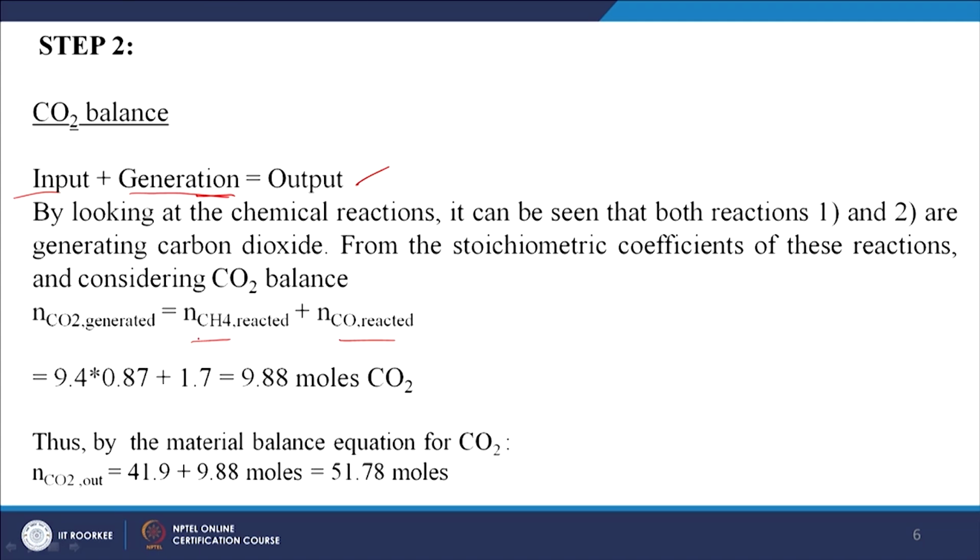And what is the number of CH4 reacted? That is 9.4 into 0.87, this part, and what is N CO? The percentage of CO is 1.7. So, out of 100, 1.7 moles was present. So, this plus this is equal to 9.88 moles of CO2 generated. So, this is the generation of CO2.